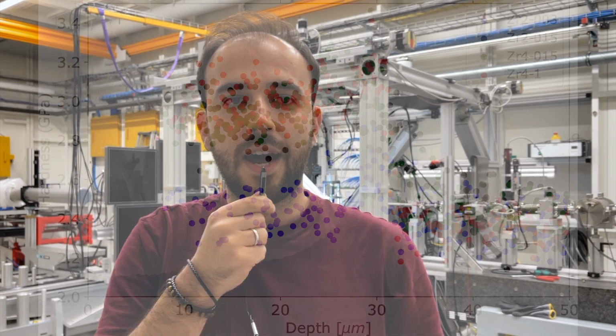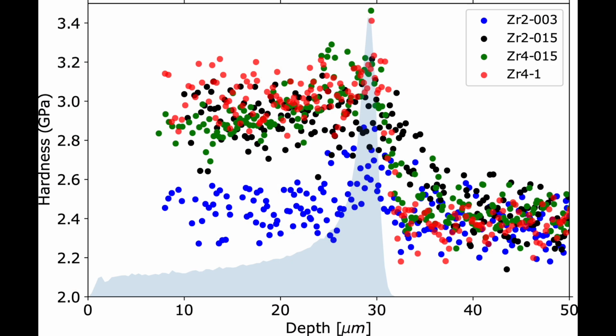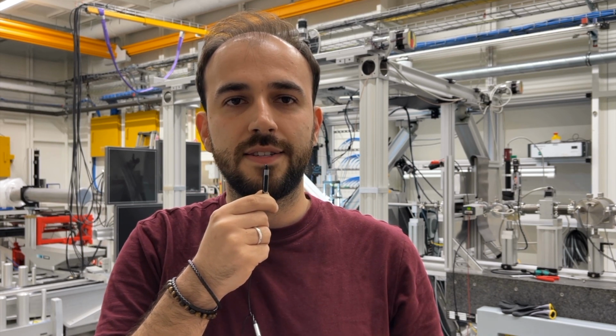Investigation of the proton irradiation depth-dependent dose behavior with the spatially resolved XRD and nanoindentation techniques showed that while dislocation density increases significantly, hardening does not follow the same trend and was found to saturate early on. This is explained using a simple dispersed barrier hardening model by introducing an XRD-generated outer cutoff radius variable. This suggests that at higher dpa levels, the density of smaller dislocation loops gives rise to higher overall dislocation density, while their strengthening effect is very small.